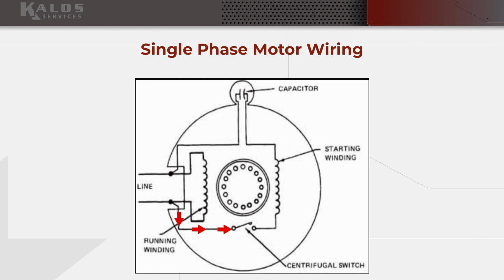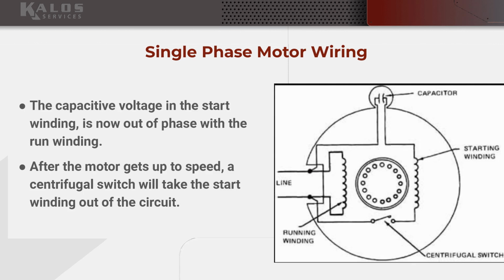And then from the opposite side of our line circuit, we're hitting what's called a centrifugal switch, which in this illustration is actually shown in a running position, because if this were at rest, this centrifugal switch should be closed, and then it attaches to the other side of the start winding. So, and then after the motor starts, let me back up.